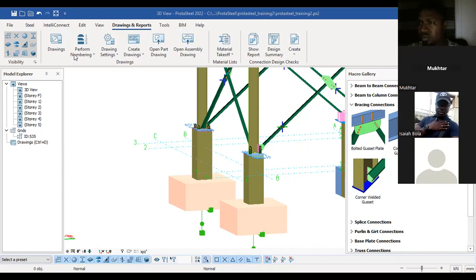Just as we did for this anchor bolt, for starter bars it will be in the opposite direction. It will extend a bit, maybe with an orientation of 90 degrees, so that it is within the column itself. It's not shooting out into the footing itself.